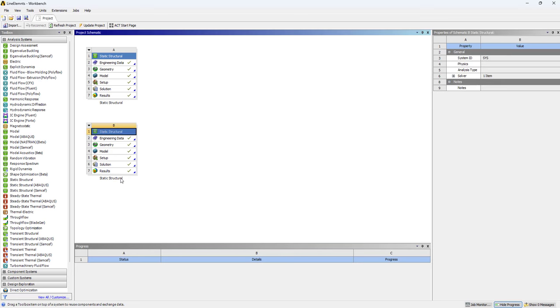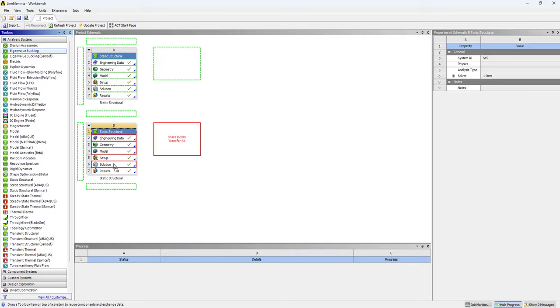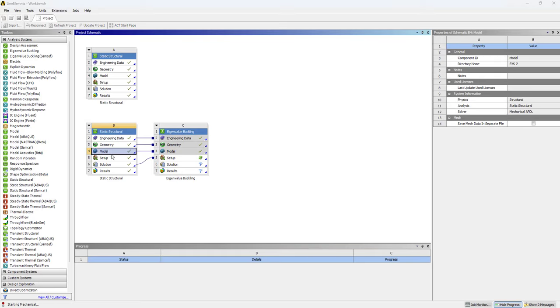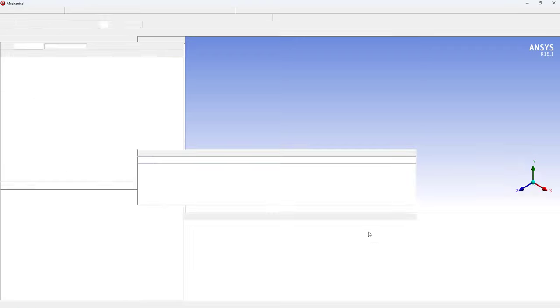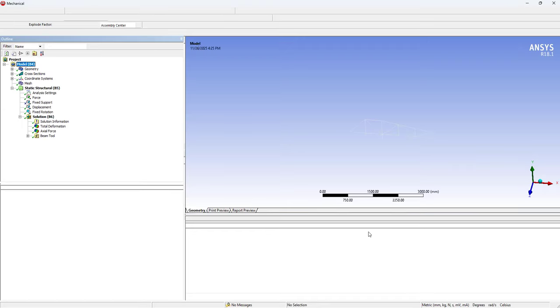I have the crane here in this structure analysis B, and I'm going to insert the buckling tool here, which is eigenvalue buckling, and open the model. After opening the model, under the given load of 6 kilonewton, we will see if the load multiplier is less than or greater than 1.